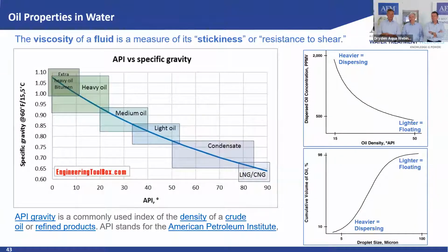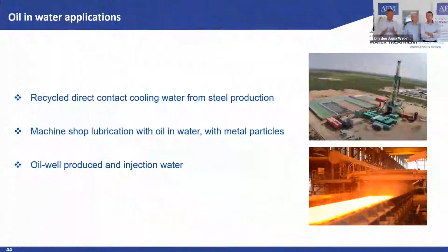Okay, so let's go on. That means there is not a rule where you can say, like with groundwater iron removal, this is the iron rule. No. You have to do it case by case and see what hydrocarbons we are talking about. A small chain is difficult to filter but easy to backwash. A long chain, high viscosity, is easy to filter but difficult to backwash. So we have to do this case by case.